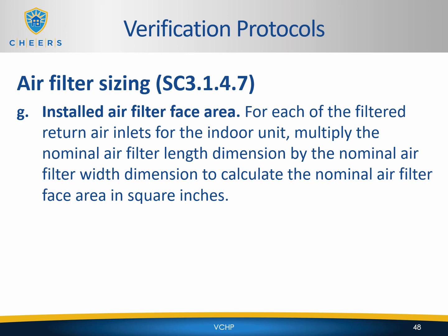Installed air filter face area. For each of the filtered return air inlets for the indoor unit, multiply the nominal air filter length dimension by the nominal air filter width dimension to calculate the nominal air filter face area in square inches.